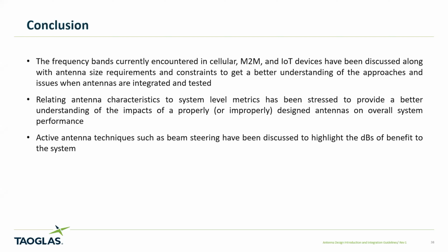So that type of information lets you start to speculate on 5G on a client-side device. As we introduce 4 or 8 antennas in a device, how often is it going to be driven as a MIMO system, and how often is it going to be using adaptive beamforming to form effectively a 4 or 8 element array? And if you form that 4 or 8 element array, you can decide what you want to null out and interfere with and apply power on target, or whether you are just concerned about optimizing radiated power back at that node.